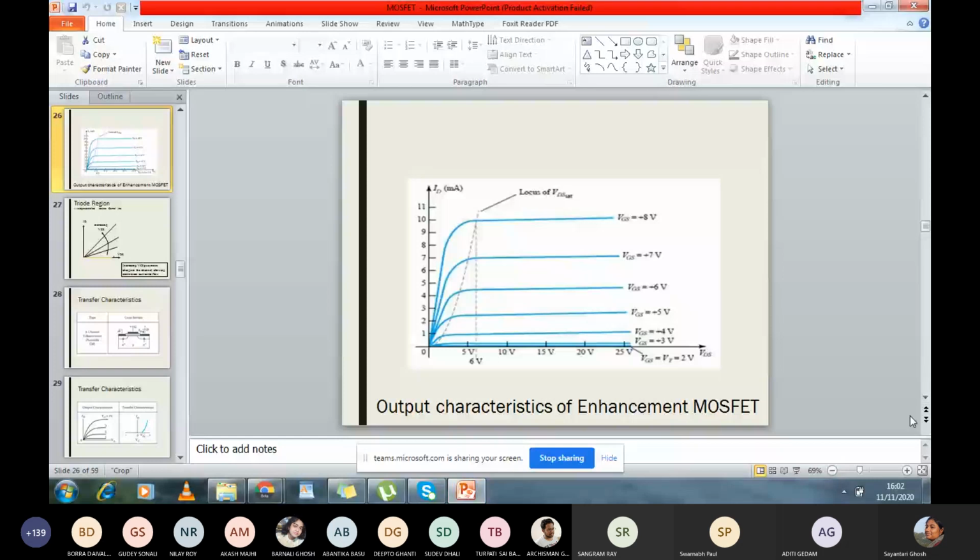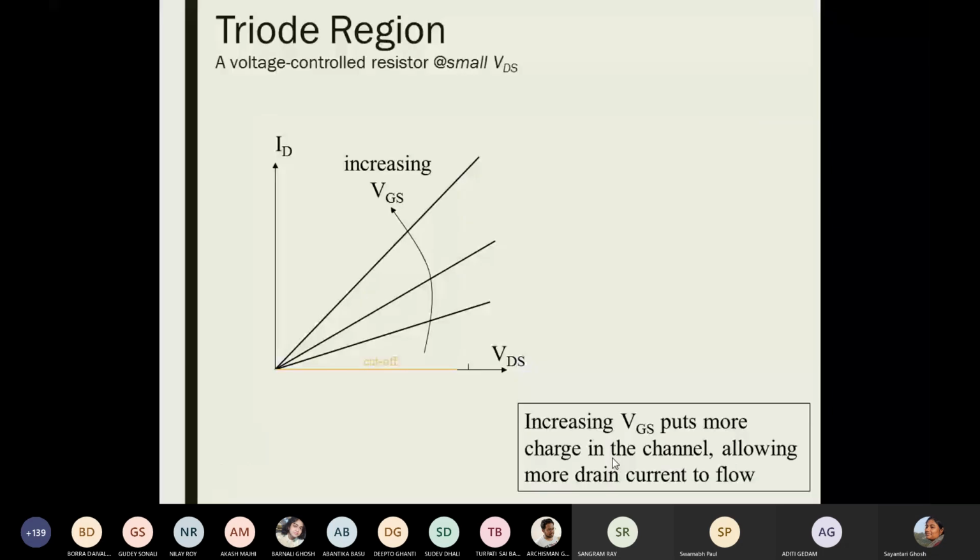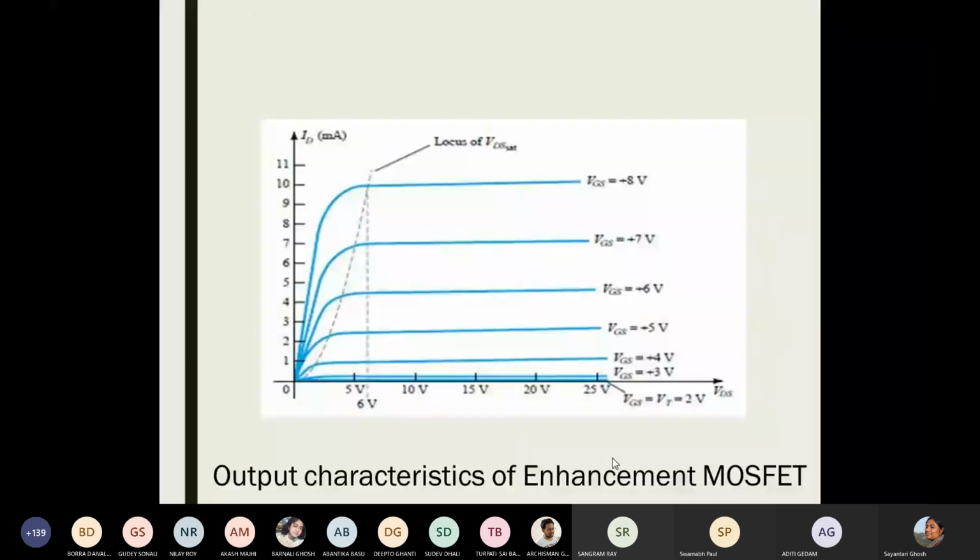So here was the output characteristics, right? And we already know from the JFET how to extend the knowledge from the output characteristics and transfer it in terms of transfer characteristics, where the y-axis will be ID and the x-axis will be VGS. Two important things in this curve: the first one was the changing slopes, which we have to take into account.